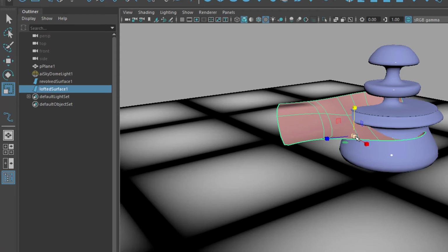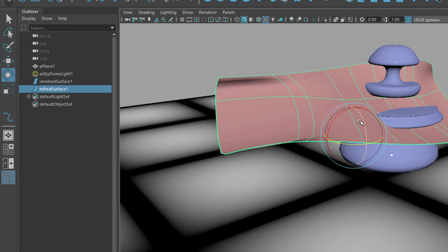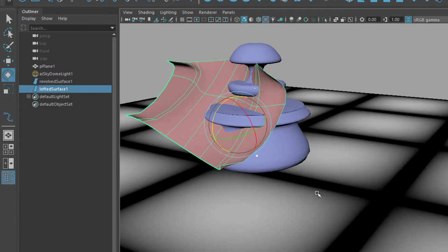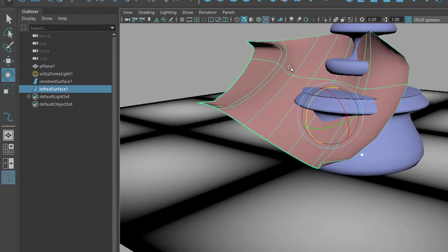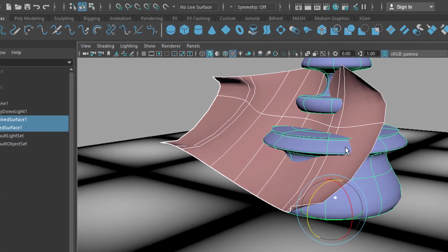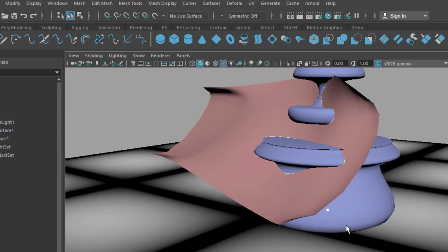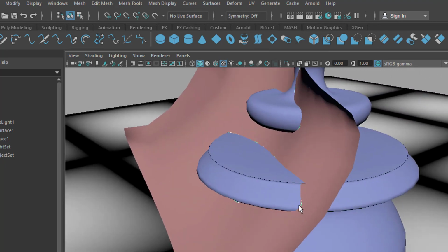Now scale it a little bit up, and I rotate it like this. So what can I do now with a cutting process? This is a very smooth, elegant surface, this one as well. So I select both of them, and I go to Surfaces and Intersect. I intersect them. So now I already see there are curves on the surfaces here.